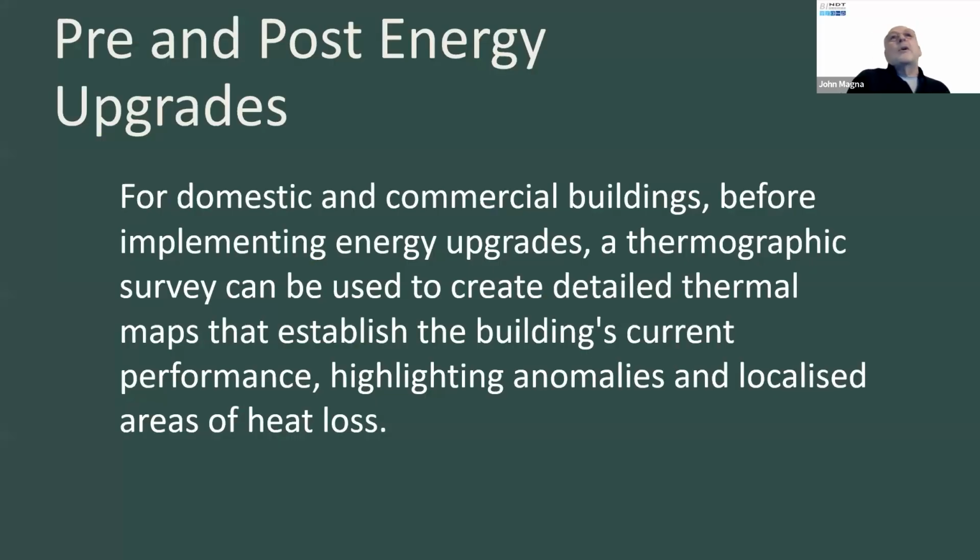Pre and post energy upgrades, for domestic and commercial buildings, thermographic survey can be used to establish the building's current performance. And we can highlight anomalies and localized areas of heat loss. Survey report can help inform developers and builders where weaknesses in the thermal envelope exist and assist in directing resources effectively. Typically reporting by exception, in other words, just highlighting anomalies and ensuring that the area is referenced for positive identification in the report. In general, still qualitative, comparative images are all that's required.